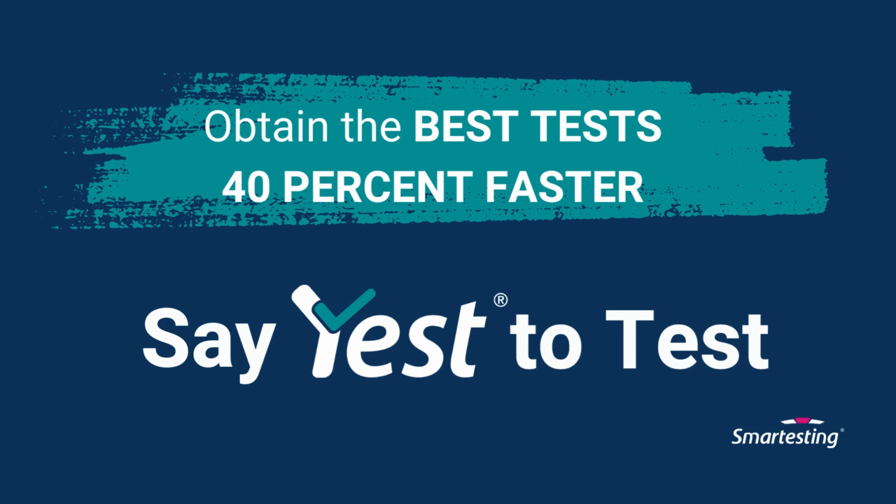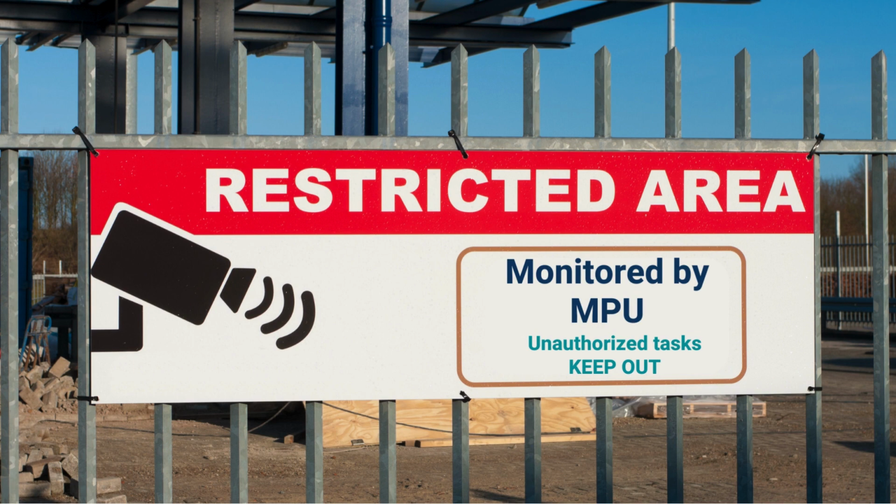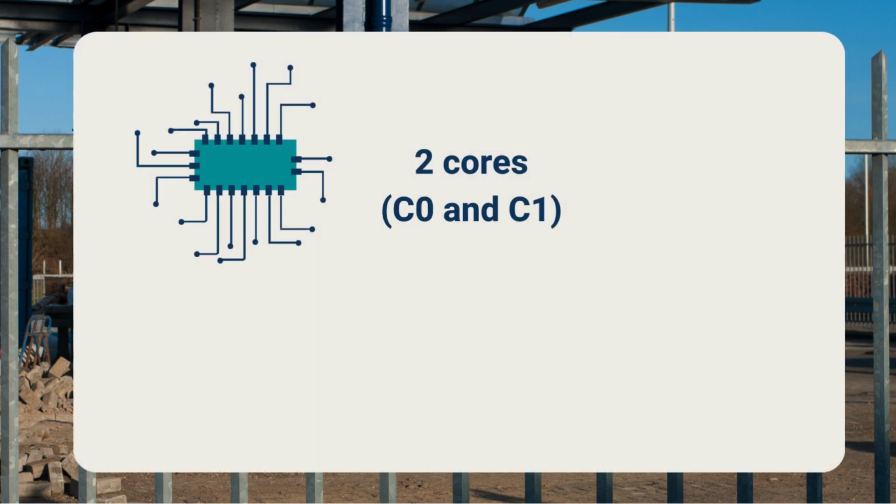In this example, the system under test is a memory protection unit used for automotive or other safety-critical software. The MPU guarantees freedom from interference of different tasks. To make sure that tasks do not corrupt memory content used by other tasks, memory areas are defined. The MPU then ensures the tasks cannot access memory areas which are not configured for them. The configuration of the MPU can be rather complicated.